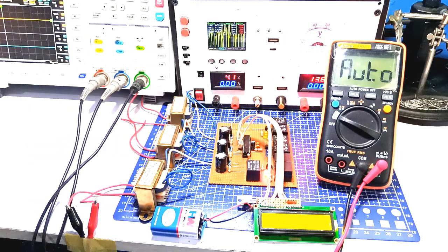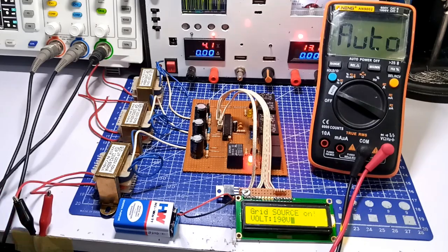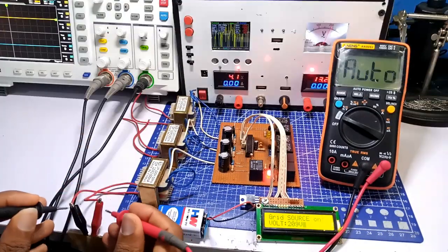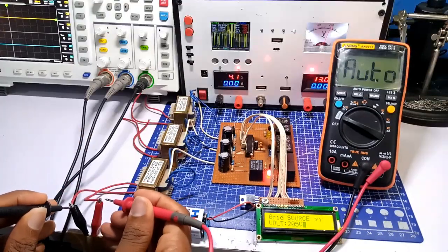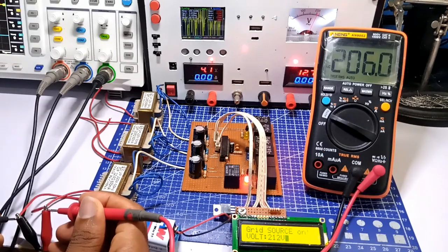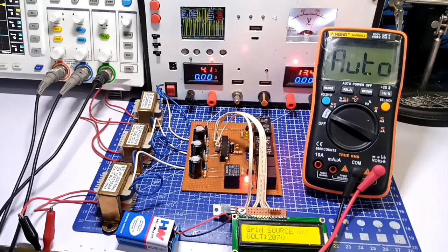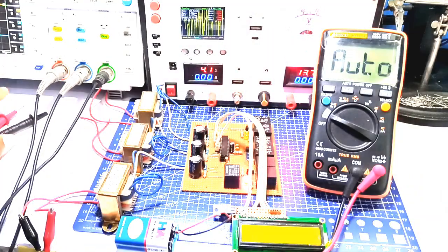With the calculation that I made using these resistor values, this resistor network can read AC voltage up to 500 volts without allowing its relative DC voltage on the analog pin of the microcontroller to exceed 5 volts. And for a reliable and precise reading, I would recommend you use this particular sensor for measuring voltage from 0 to 350 volts AC. With that being said, let's now go through the Arduino code for this project.